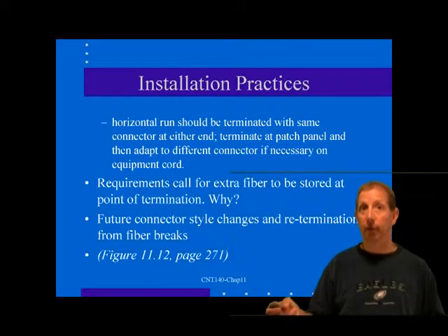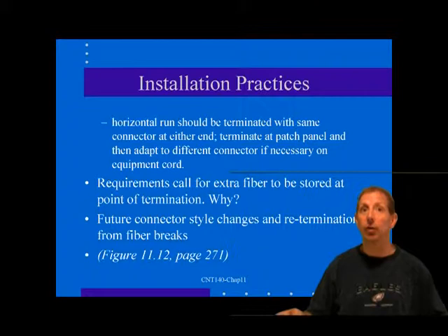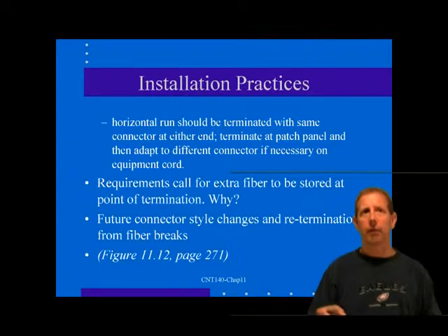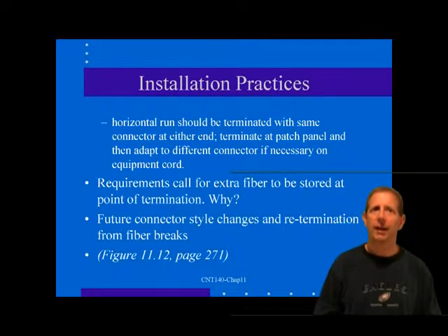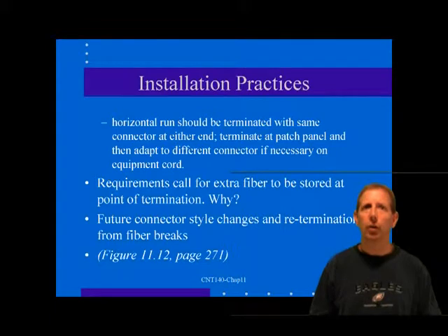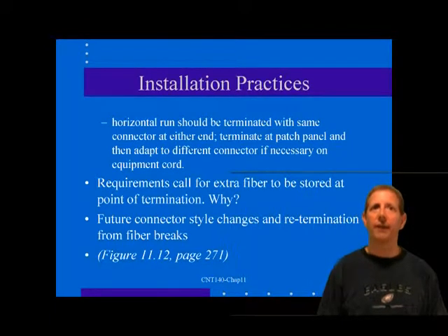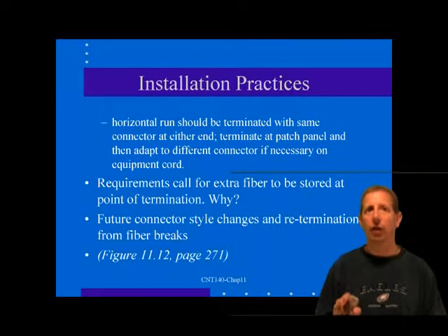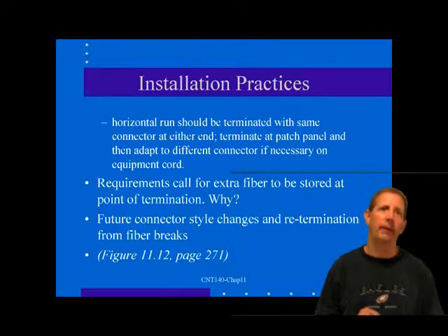The outer jacket and fiber's plastic strength members must be removed if you're using a jacketed cable. In this type of cable, the outer jacket is slid around the circumference and slipped off the end of the cable. Next, the Kevlar fibers are combed to one side and then cut off at the edge of the remaining jacket. Kevlar fibers are extremely tough and a high quality cross cutter must be used to cut them back.